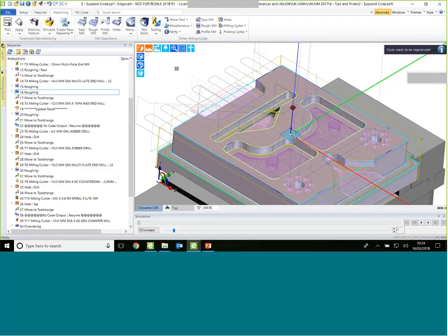That would normally begin to start doing some regeneration, but as you can see, it's not. So I could make all my edits, all my changes, I could make additions, and I don't get any extra regeneration. It's only when I say, and now turn it back on again, that I'll get my regeneration. And it's right and proper that it does the regeneration, because it's checking that every runner and rider, every single toolpath is beginning and ending at exactly the right position. But just by having that little bit of knowledge is always a nice thing, just to hold back that time.